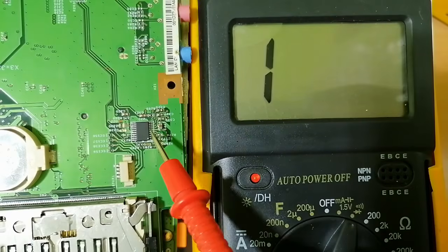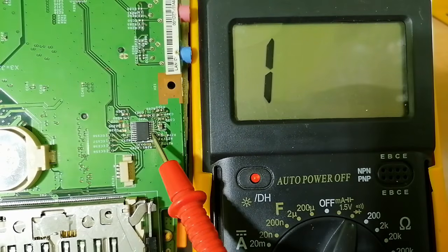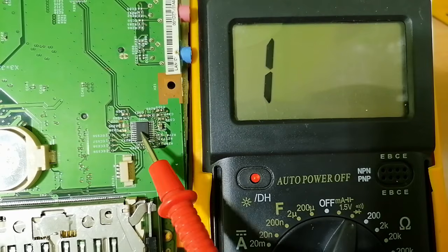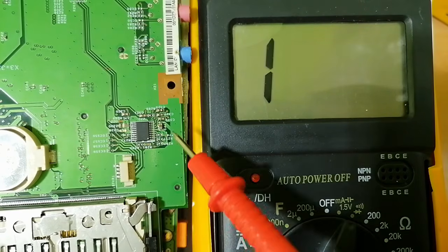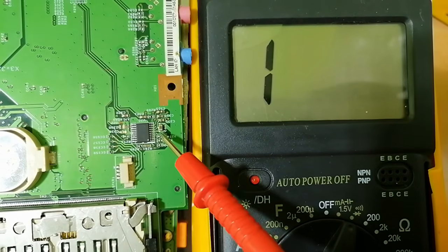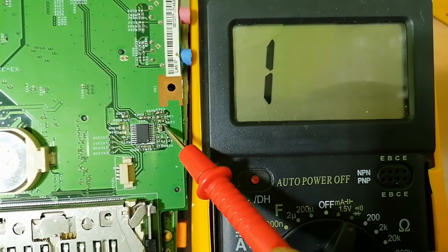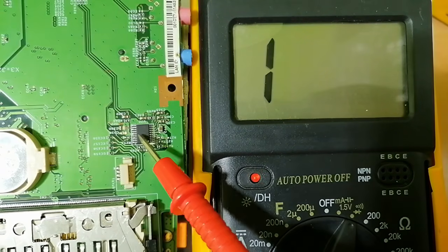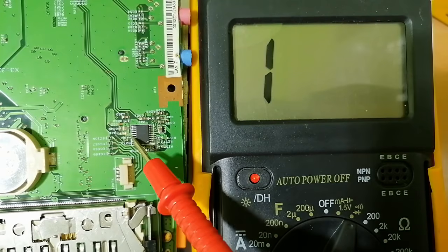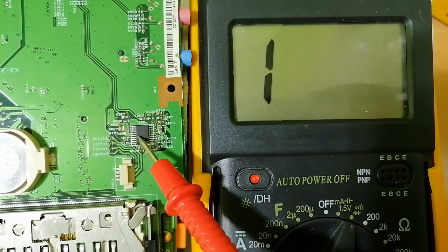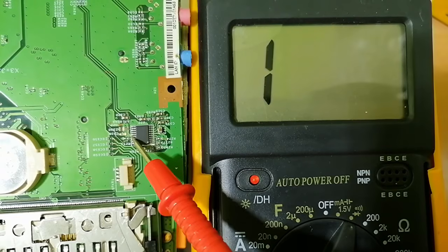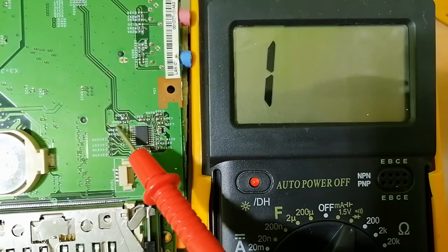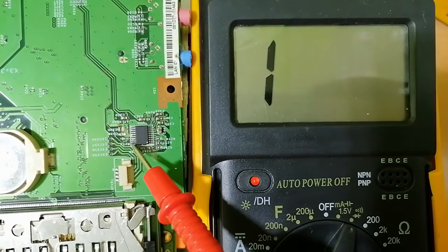Okay, so this information right now we will use to find a short circuit. Because the ceramic capacitors are connected to the IC on one side and to the ground on the other side, and of course the IC itself is connected to the ground in one or two of its pins. Do you see here? These 2 pins basically are connected to the ground, as you can see. Why? Because we have this bolded path here, means this is the ground.